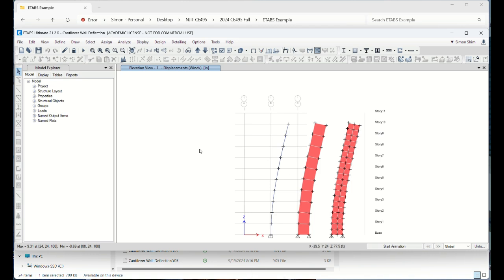This is mostly fundamental, the characteristic of the internal finite element theory inside. They overestimate because the 2-point area element overstates slightly compared to the line element. Maybe because they have support here, two supports, it has a tendency to overestimate. Also, we are using a coarse mesh, one big plate, which means this one versus this one is slightly different, because this one I just divided by 2 by 2, right?